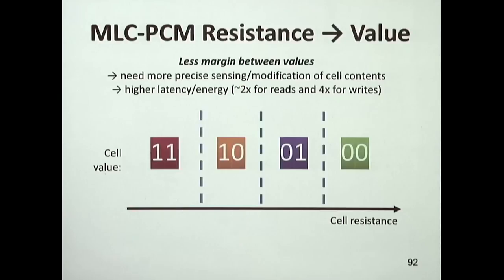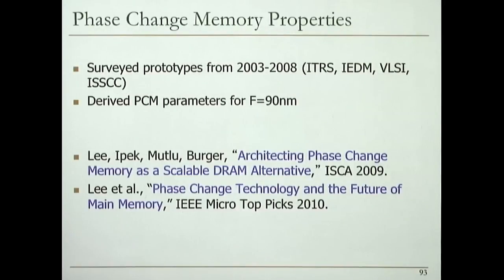You need a very, very specialized sense amplifier design, which really complicates and increases the cost. There is a cost increase over here, again, but it's more reliable. OK. Does this make sense? So this is how you can increase the density without actually changing the capacity, or without actually adding more cells. Right? That's what I meant to say, actually. Because it's the same cell that stores 2 bits. If you want to store 3 bits, you divide into 8 ranges over here.